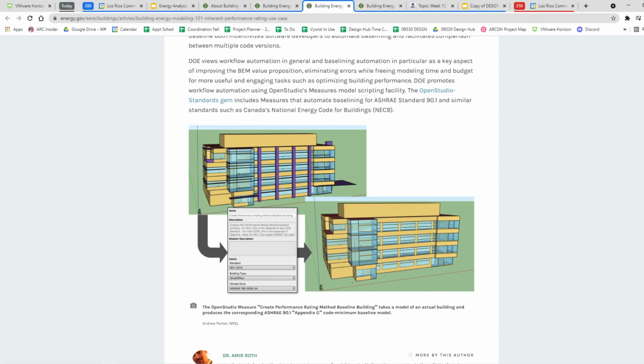So, for instance, if it saw one portion of the building would get a lot of use a little bit early, and you could warm up that building slowly a little bit beforehand in that area, then you wouldn't have such a shock load and you'd have better energy performance. Or if it saw that there was very little occupancy in a building at a certain time, instead of waiting for the CO2 levels or the heat levels or the inherent heat loads to go up or down, it would do it predictively.